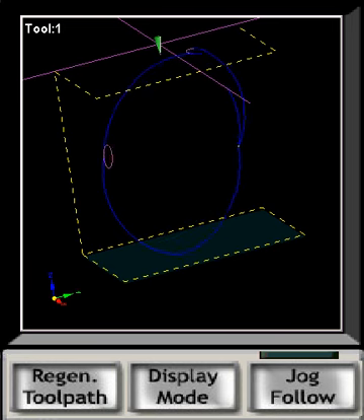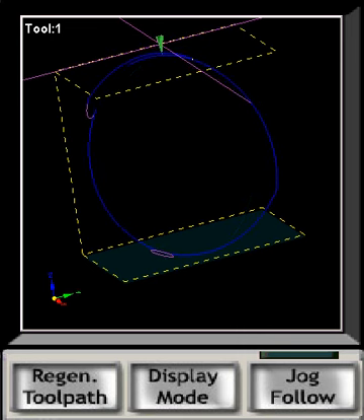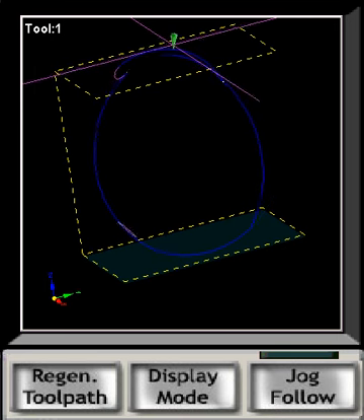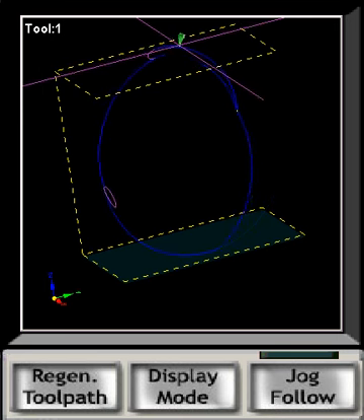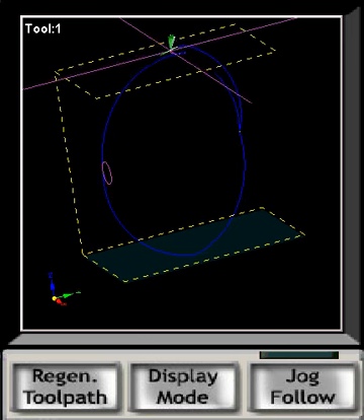Again, the A-axis display is a little bit harder to use at the moment because you have to understand something about offsets and where you're positioning your rotary table. But as long as you position your rotary table in the machine coordinates that you've specified, you really shouldn't have too much of a problem in terms of making it work.